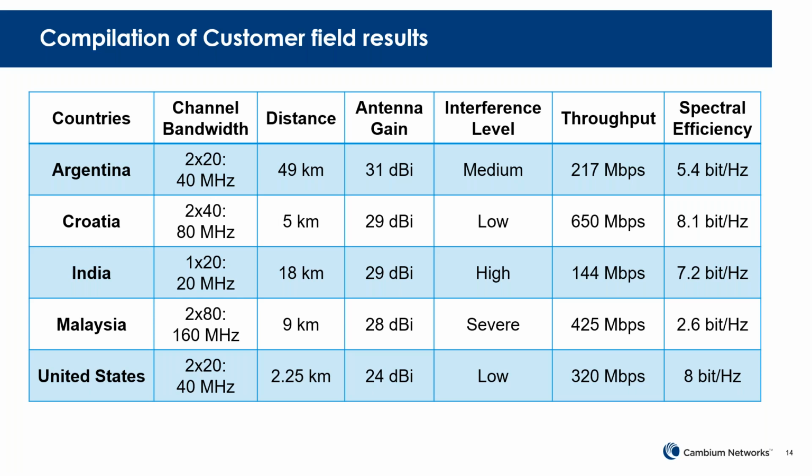I don't remember the final answer for that. But certainly you don't need a whole channel bandwidth for the guard band. If you have two 40 megahertz channels, you don't need a 40 in between. I think it was like 5 or 10, but I need to double check for that one.